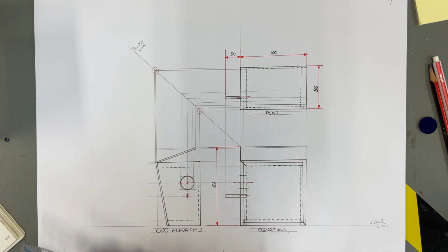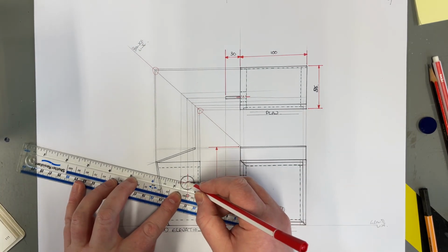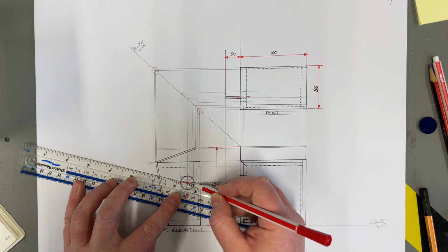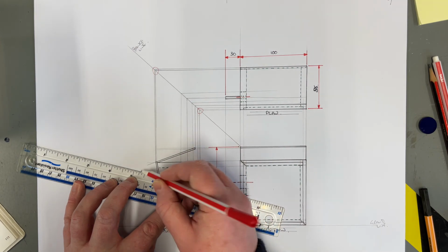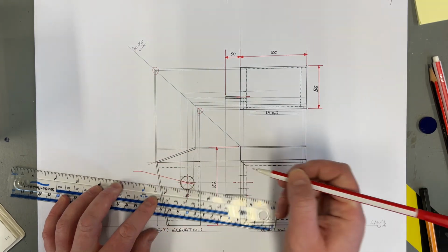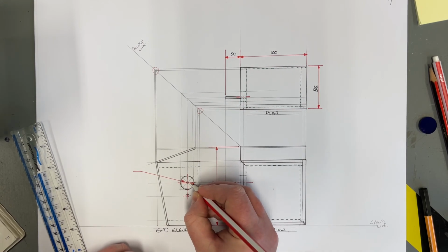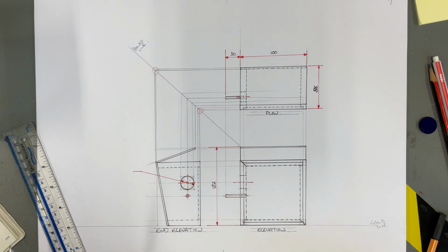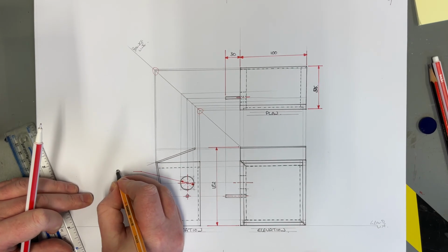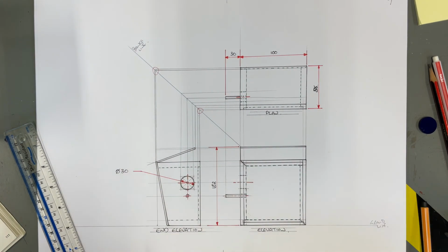The only other one that I would definitely want to put in there is a dimension for the hole. That's a critical dimension because we need to use a particular size of tool for it. So the leader line would go straight through as if it was the diameter, all the way through and outside the object like so. Would then make that horizontal. Put in a short, sharp, filled in arrowhead, like so. And for diameter symbol, and then 30 millimeters, that would be cut with a 30 millimeter tool.